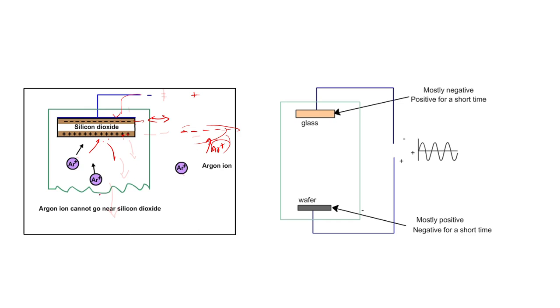They will start moving towards the substrate, but once they have moved some distance, again the polarity will change to positive. So it will again get attracted towards the target. But the electrons will move easily between the substrate and the target material. So that is what happens.